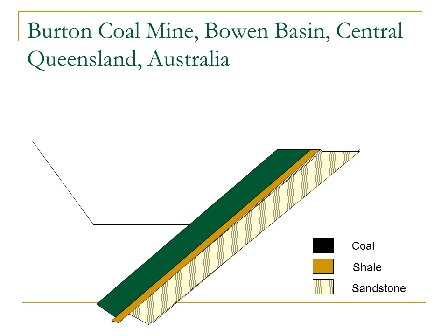This is a case from Queensland, Australia, that I had an opportunity to get involved in the analysis of, where they were looking at a coal seam, and after they extracted the coal seam, they were left with a relatively thin shale layer on top of sandstone. Well, when the wet season came along, they suddenly had their shale layer sliding into the mine, making it unstable. What happened is, as they removed the coal seam, what was left was a thin shale layer on top of sandstone, and water would build up in the sandstone behind the shale.